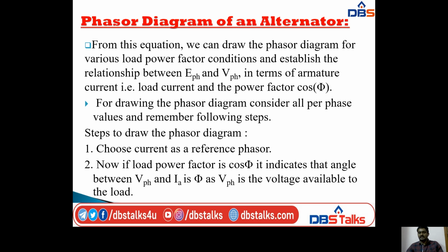If you want to draw the phasor diagram of an alternator, you have to follow some steps. I will discuss how to draw the phasor diagram. The first step is to choose the current as the reference phasor. If you want to draw the phasor diagram of an alternator at any power factor condition, we take current as the reference phasor.